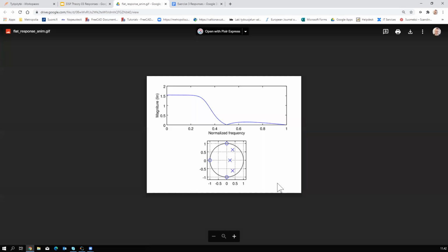Okay, another thing. Poles are usually used to either adjust the gain on certain frequency to get high Q factor, or as in here, it flattens the magnitude response on the passband.